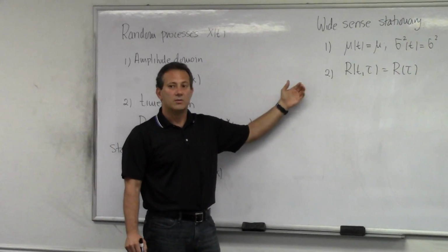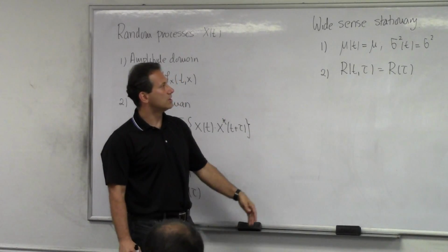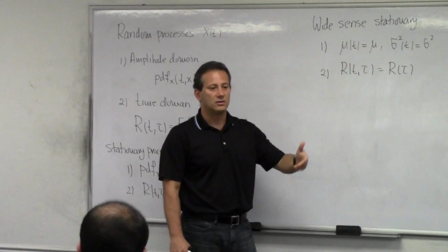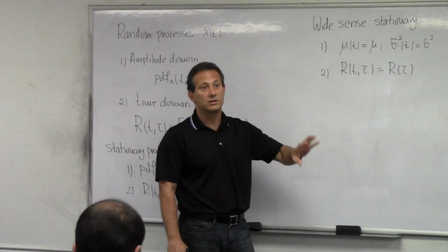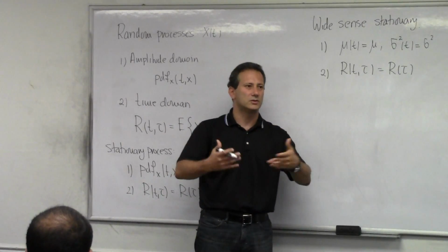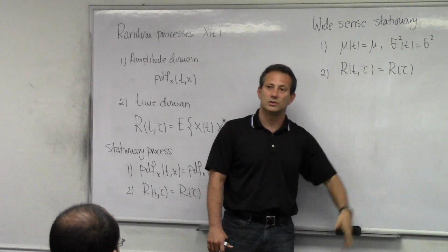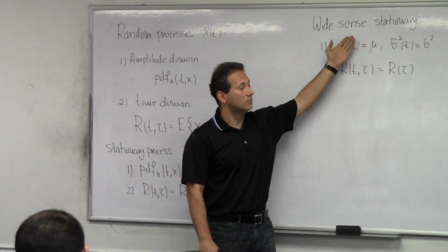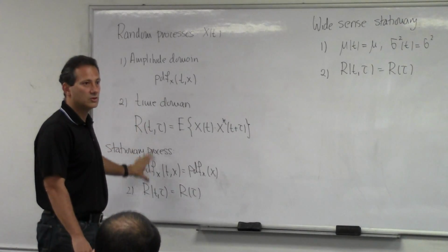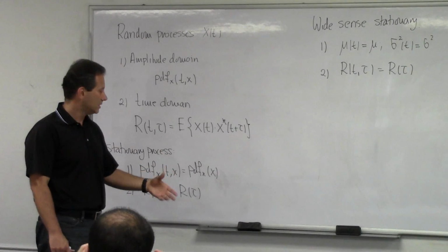Why is this an important category? Because a lot of our signal processing algorithms and a lot of our, I guess, analysis in general requires that the mean value of the signal and the power of the signal stays constant for us to do something, right? And we rarely pay much attention to the higher order moments. There are algorithms where this is also concerned, but in most of the algorithms that we deal with, especially when you talk about signal to noise ratios and those kind of things, then you really just talk about the powers, the ratios of the powers, and it's important to say powers do not change over time. Powers are stationary, and this is, as I said, weaker condition that's satisfied obviously more times than this stronger condition here. This is a very strong condition. You require that the entire PDF does not change over time. Nevertheless, some of the most important processes that we deal with are kind of stationary.